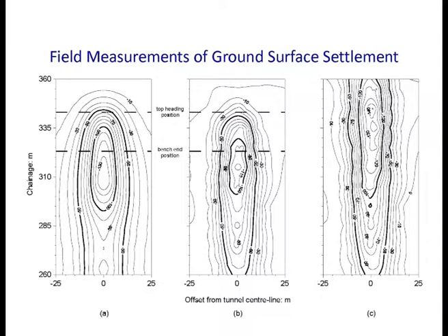And when we compare this thing with this thing, you can see this is perfectly symmetrical. This is the only thing. Finite element, you do this, it has to be perfectly symmetrical. So basically, when you look at this, this is about 130, slightly more than 130 millimeter maximum settlement. And if you look at this, this is about 120 odd. So the difference is about 10 millimeter of settlement, and the difference is about 10%.